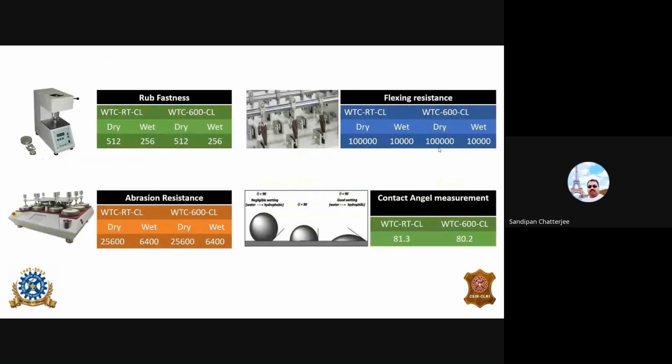And finally, we have tested the coating performance of the leather. We have done roughness, flexing resistance, and abrasion resistance in dry and wet condition. This is basically a performance of the coating composition, that is, the formulation. It is showing that in case of dry roughness, all the materials are very excellent. But in case of wet, it's not as good as the dry, but it is still comparable to the marketed product.